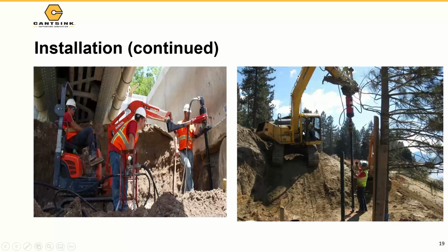piles. And we're using a bigger rig because this 4.5-inch pipe has a rated torque of between 20 and 25,000 foot-pound. So if you use a small Bobcat, it's so slow. So we have to use a bigger rig and bigger torque motor to install this 4.5-inch pipe.